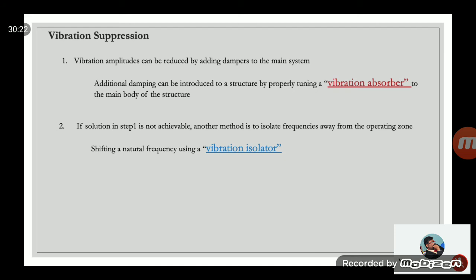In that case you have to find another way of controlling this amplitude or controlling the situation. So in that case, you can also design a vibration isolator. Isolator in the sense it will isolate frequencies away from the operating frequency. That way, your natural frequency will be away from the operating frequency, and there is no vibration at all.